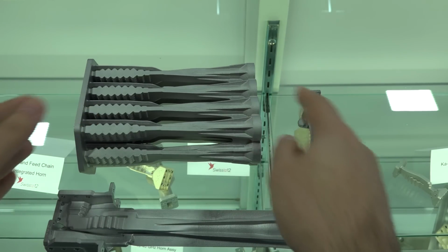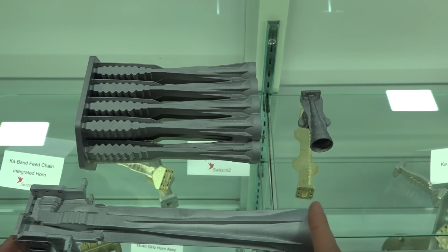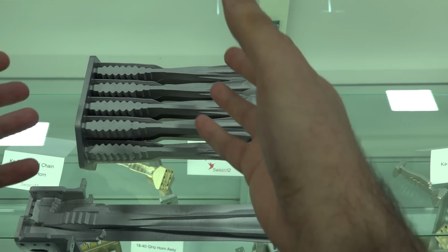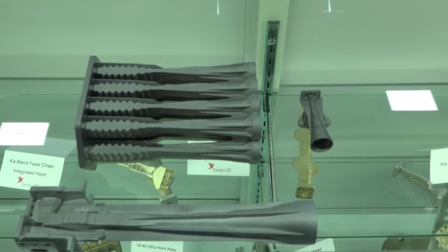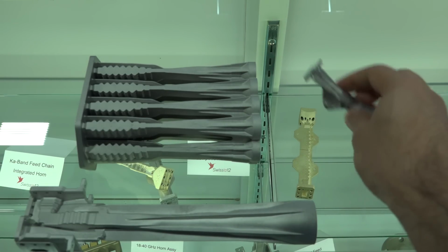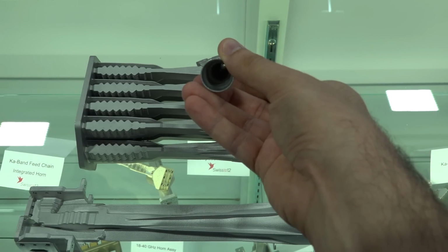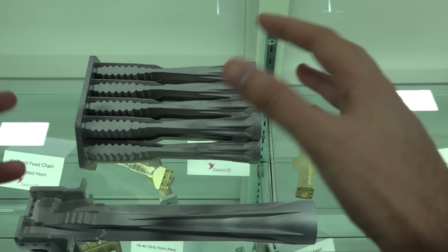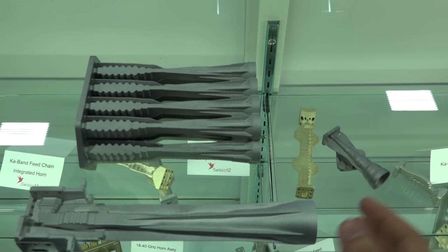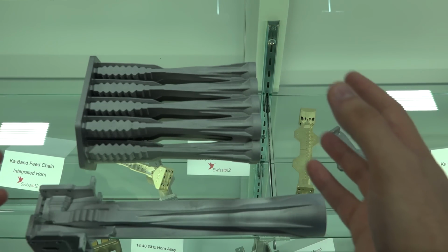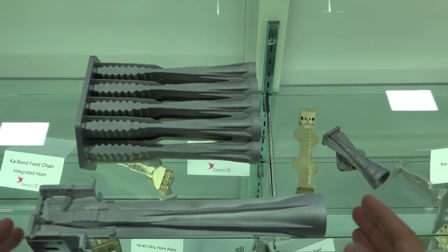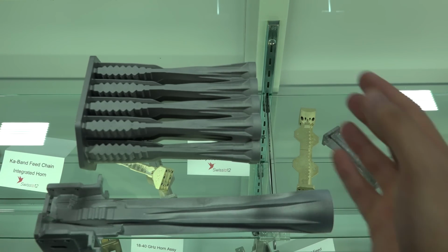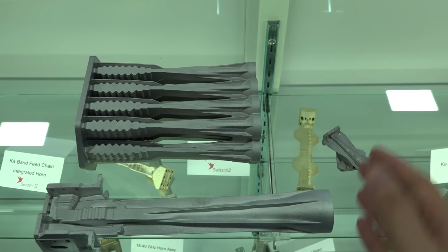It would be cheaper to manufacture. You can do all these crazy transitions in between without incurring the loss and the machining required to put everything together. They've also explored even higher frequencies up to Q and V band. You can see these features continue to get smaller and smaller. But imagine that you want to create a very complex filter bank that has 2 or 4 different frequencies at the same time. You want to transition in and out of that. How would you go about doing that using a CNC? You would have to build it in pieces. Here you're growing this all at the same time.